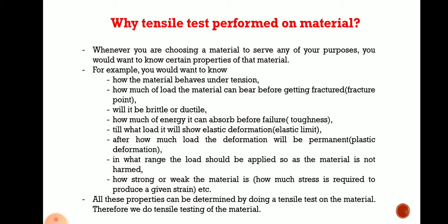So for that purpose we will study here the tensile test, and in the tensile test all these properties such as toughness, elastic limit, plastic deformation, again what is the fracture point, whether a material is ductile or brittle, what is its tensile strength, what is its yield strength, what is its ultimate tensile strength. All these things we will find out by using this tensile test.